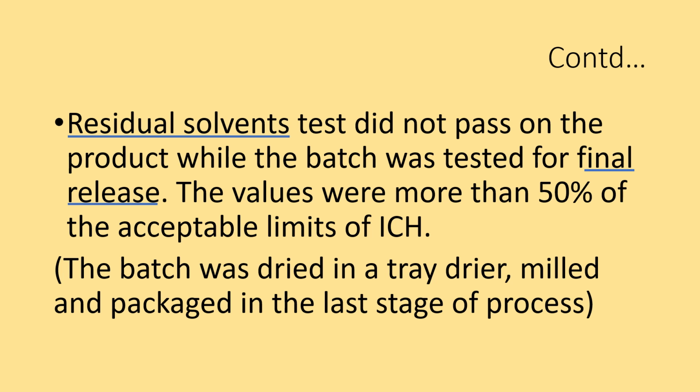Here it is necessary to look into the drying trend of the product. Was it dried within the normal time frame, like 6 hours or 8 hours as per the batch record? If not, the operation of the dryer is the culprit for failure. Generally, a water content test or a loss on drying test is considered as the in-process checkpoint for completion of drying.